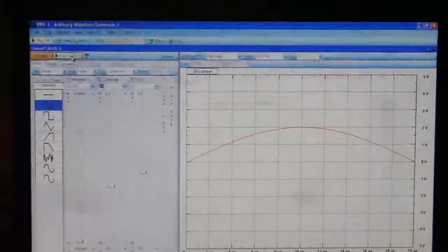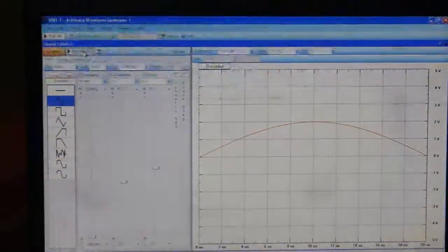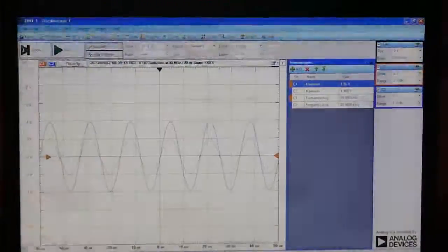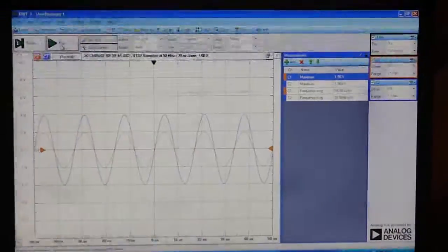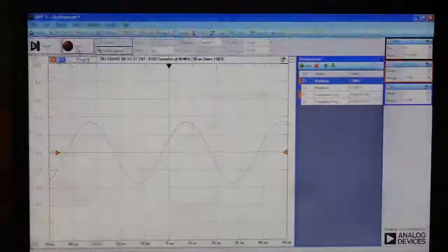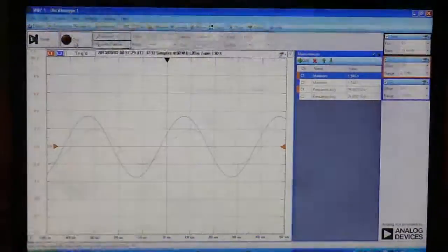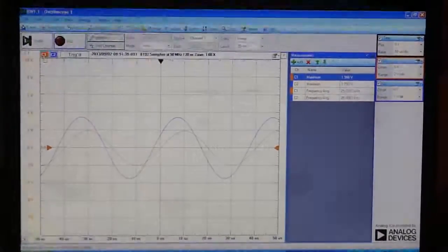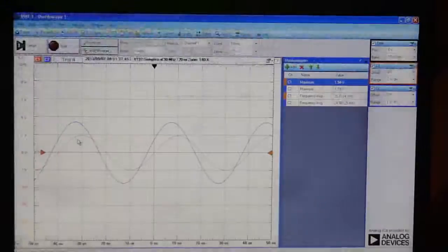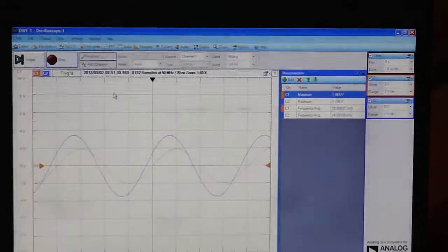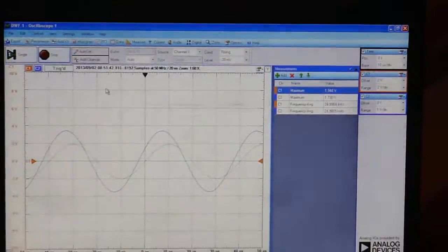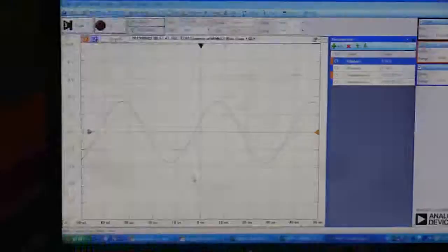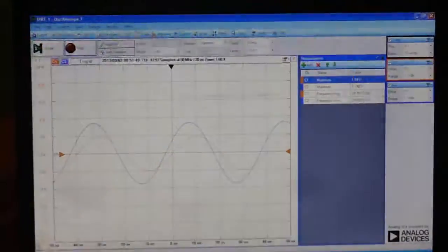I'll click upon the option Run Automatic Waveform Generator, and then go to your oscilloscope, and in the oscilloscope click upon the option Run. So as you can see over here, channel 1 captures your input signal, whereas channel 2 captures your output signal. The purpose of this experimentation is to draw the frequency response of a passive bandpass filter.